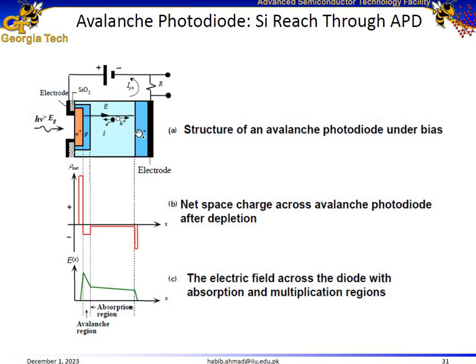Now let us focus on this configuration. We know here we have an NP region. We know from the concept of the depletion region that inside the I layer adjacent to the metallurgical junction we have uncovered positive charges. Similarly, in the P region adjacent to this metallurgical junction we have uncovered negative charges. In the I layer, we don't have many uncovered charges. We just have the electron hole pairs generated as a result of these incoming photons.